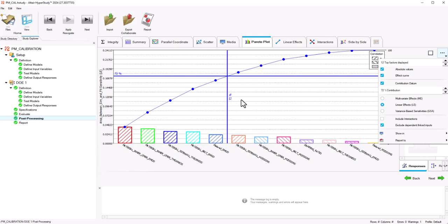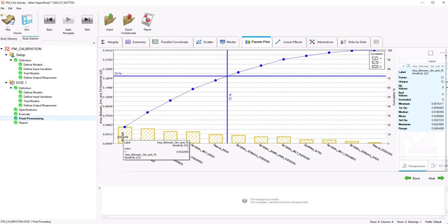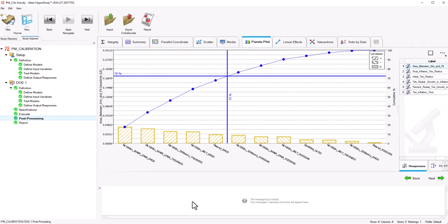And perhaps you want to increase or decrease this, but the Pareto plot is giving us the approximate influence of the input parameters on the response. So the next step here is to verify that for the output response that we got, the response of the simulated tire fully encompasses the measured response.